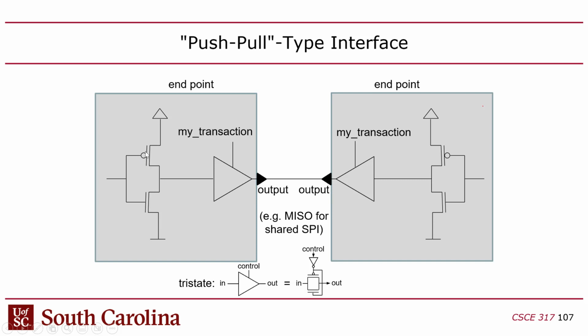One transistor is responsible for setting the output pin to 1, and the other one is setting it to 0. The problem with this arrangement is that one or the other transistor is activated at all times, which means the pin is always being actively set to 0 or 1. And in that case, what you're trying to avoid is a conflict where one chip is pulling it to 0 and the other is pulling it to 1.